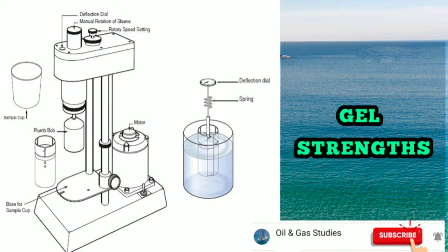Applications: the gel strength quantifies the thixotropic behavior of a fluid, its ability to have strength when static, in order to suspend cuttings, and flow when put under enough force. Ideally, the two values of gel strength should be close rather than progressively far apart.